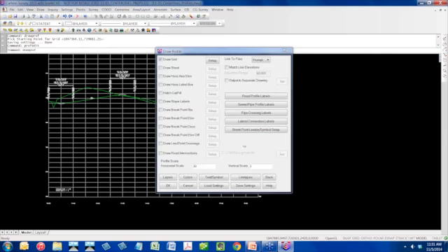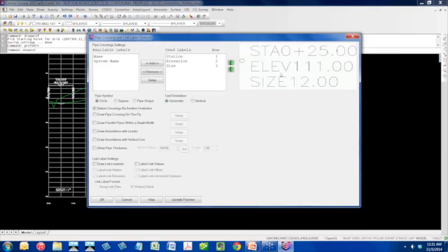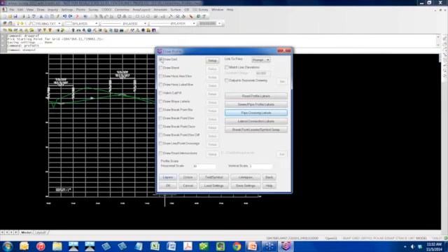So here's the trick to this one. Two things. One, pipe crossing labels. Right now, it's just something very generic like this. Okay. I'm going to uncheck Draw Grid. Okay, so if I already have a profile on a grid in the drawing and I just want to draw a new profile like this crossings on top of that existing grid, I uncheck this.